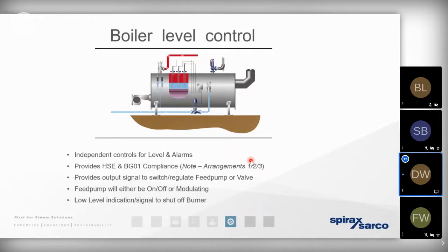And what you'll remember is as we increase the sophistication of the level controls and the pump configuration, it means we're more likely to be in a position where we're distributing a condition of steam that is of a better quality. If we've got a less sophisticated control, for example, a magnetic float sending a signal to an on-off pump, that means we're more likely to get that wet steam that we want to try and keep away from.